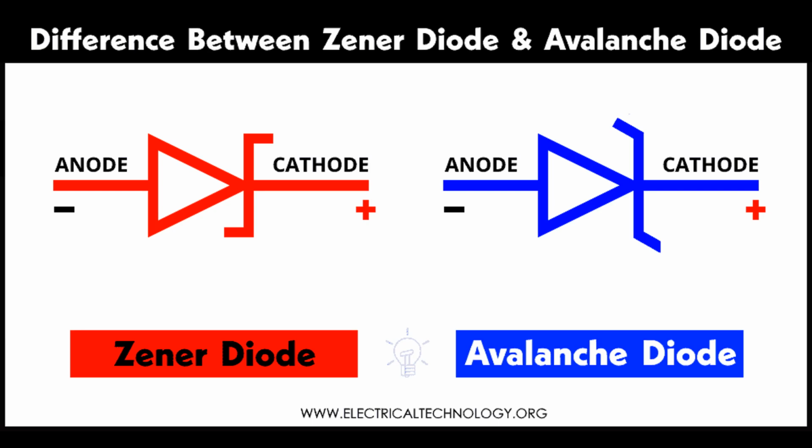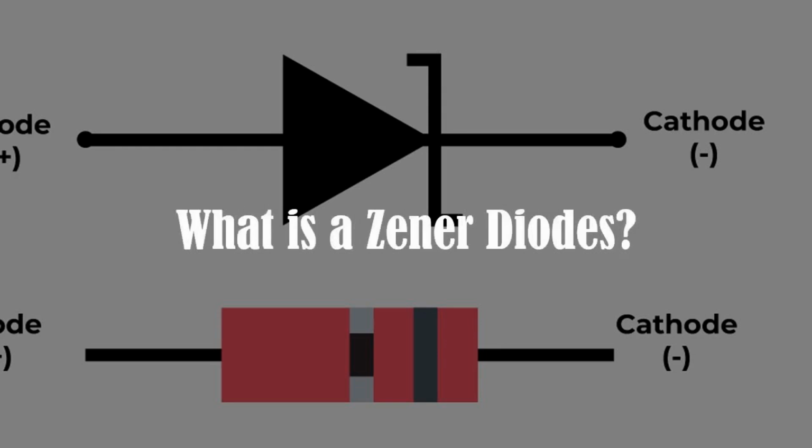Characteristics. Tighter tolerance on Zener voltage, as low as plus or minus 0.5%. Lower temperature coefficients, providing better stability over a range of temperatures. Often used in low noise and low drift applications. Applications. Precision voltage references and measurement equipment, ADCs, DACs, and other high-accuracy applications.